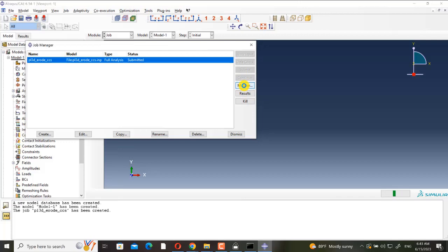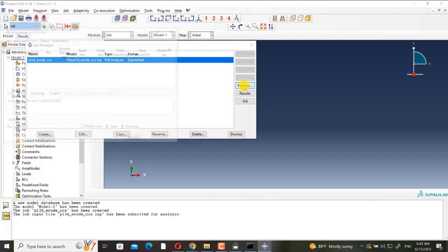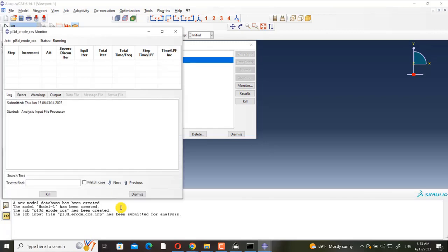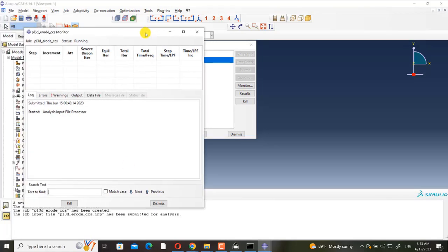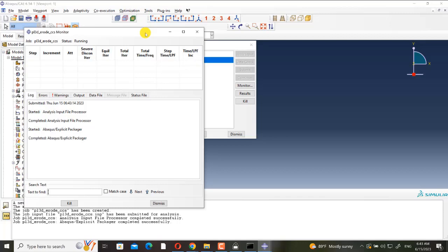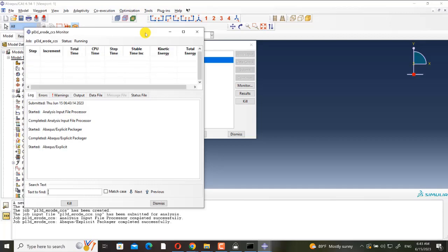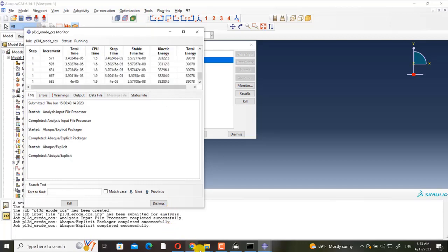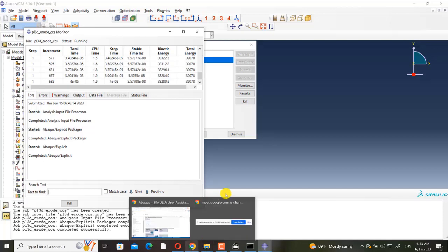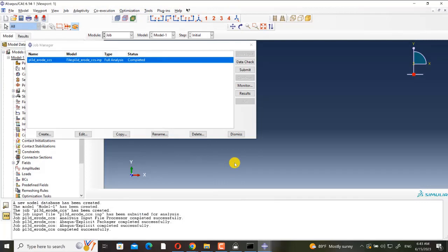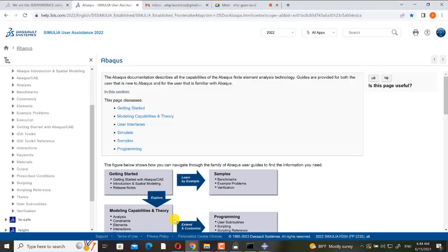And also, they don't share the CAE files because they are very valuable. All of the efforts that you have done are in the CAE file, so it is very, very valuable. If you search in Google or LinkedIn, most of the people don't share their CAE files because they are very valuable. They only share INP files, okay? Because they cannot be imported correctly. A CAE file is changed to an INP file correctly, always correctly. But it will not be done in the reverse direction always correctly.